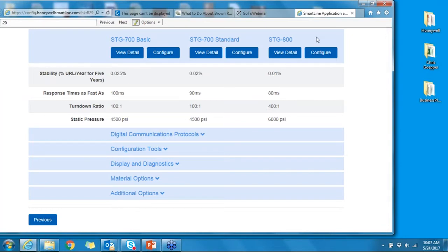The first screen that you will see is an opportunity to select the different types of units that might be used. So for our example, we'll keep it simple. We'll go to pressure. If there's going to be a temperature displayed, we'll make sure it's in Fahrenheit. And even though in pressure there's no length in units, I'll just switch it to inches just for the heck of it. Go down a little bit further, and a variety of different types of pressure transmitters we could pick from. For our example, we'll just select gauge pressure.